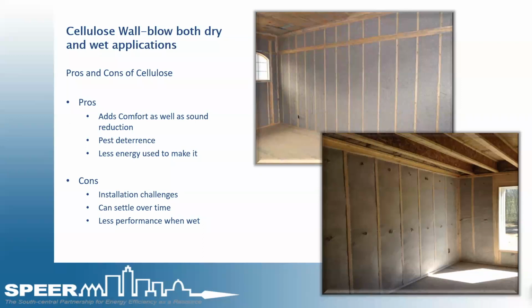Cellulose wall blow, both dry and wet applications. The pros are added comfort as well as sound reduction. It's got a pest deterrent in it. It's also got a fire retardant in it, and it uses less energy just to make it. It's ground up newspaper and has a borate treatment that's been sprayed in it.